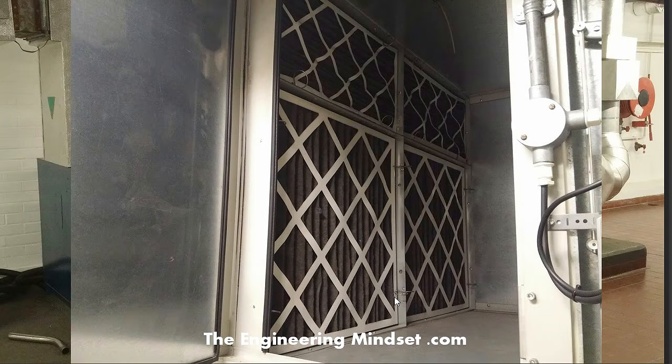So this is how they look inside the AHU. You can just move there, they're very light, and you can just slide them out like this also. Sometimes they'll have these clips here, so you can't slide them out. You just rotate these and pull the clips off, take the panels out by rotating these.